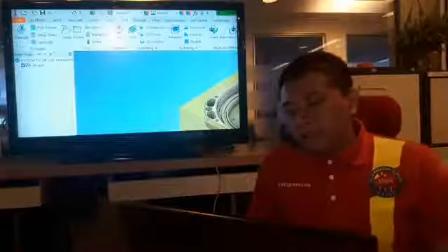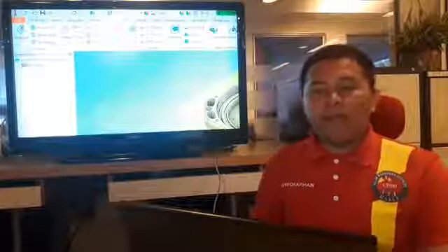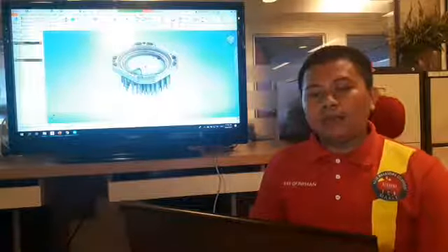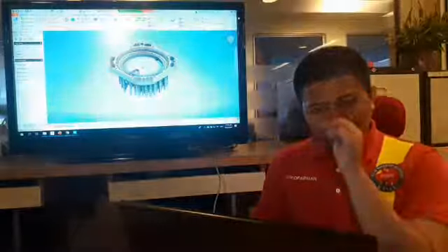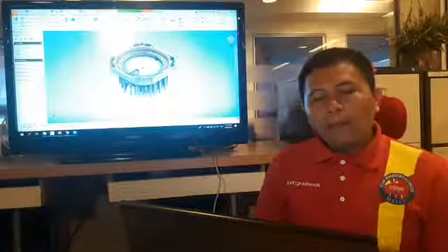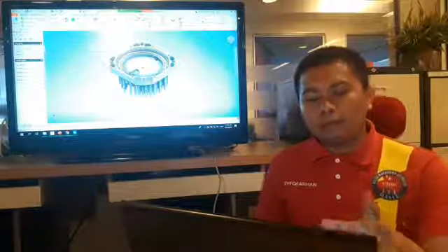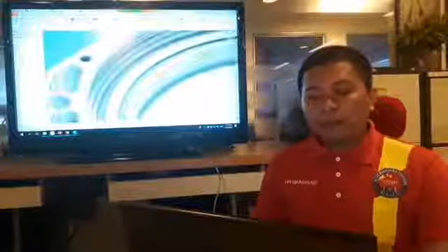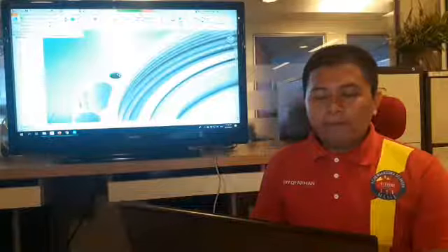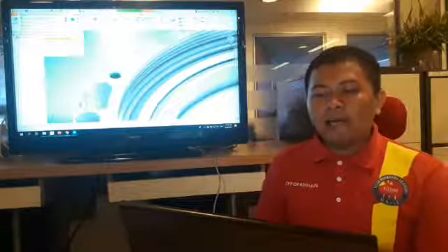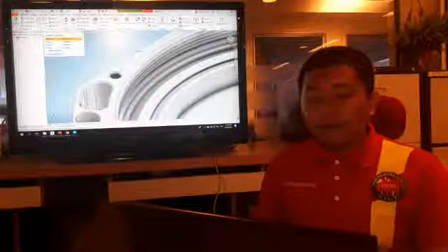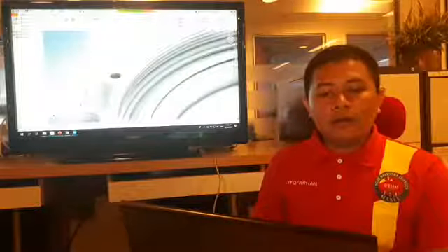So now I will start from maybe a simple step, and I choose the drill for my first job. I just simply press drill. Before I choose the geometry, the face or surface, I need to make sure that I choose the proper tools. Before I start, I need to know the diameter of this circle. As you can see, the diameter of this circle is 5 mm. Then I just simply go again into drill.